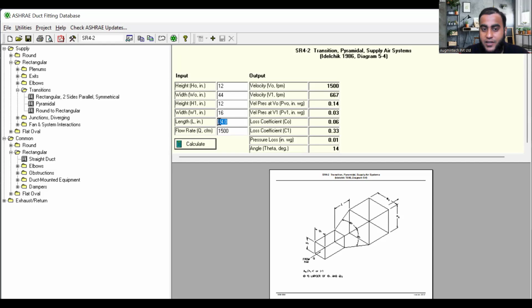Now you have to enter the length of that reducer. You see in the figure, it is given everything, okay? So you have to just see this figure, as per that, the value you have to enter. What is the length? We have entered already in Excel sheet. I have shown you 450 mm near about, na? So 450 mm means how much in inches? So divide by 25.4, you will get 18 inch. Yeah, near about 18 inch. Just enter the value 18 inch.